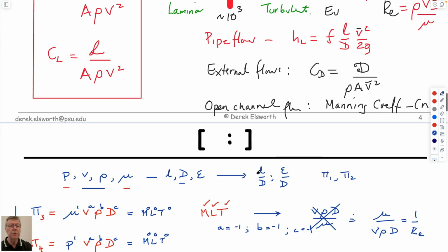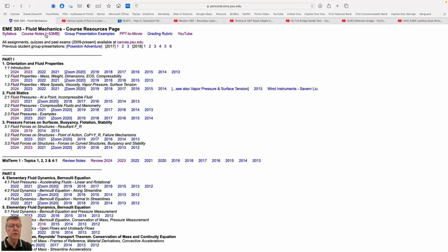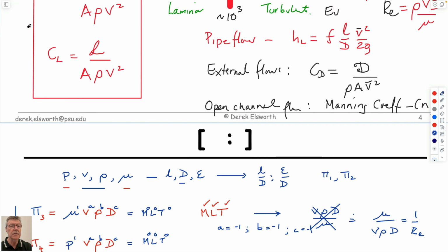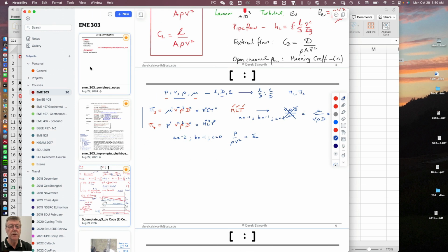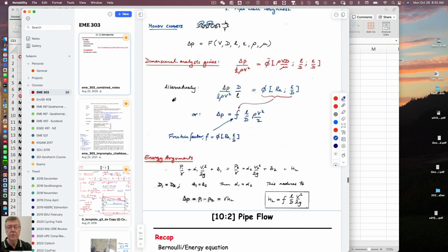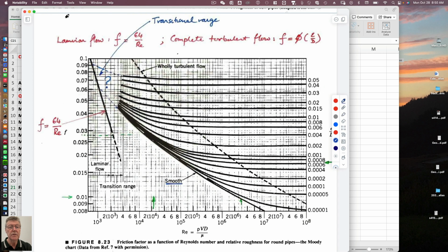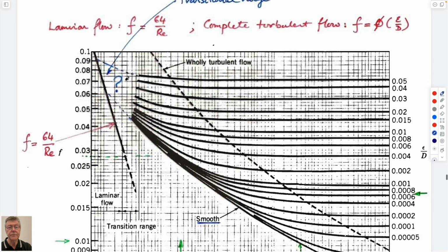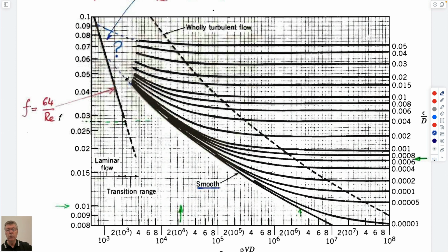And so maybe next time we'll talk about how we actually use this. To use this for our systems, we didn't go through this analysis, but we will use a figure like this, which is exactly what we're looking towards. And so this is the so-called Moody chart, which says that in a laminar regime, our friction factor, which controls flow, is a straight line.